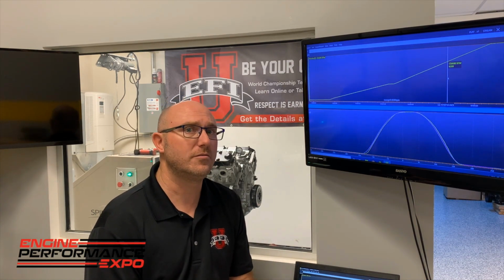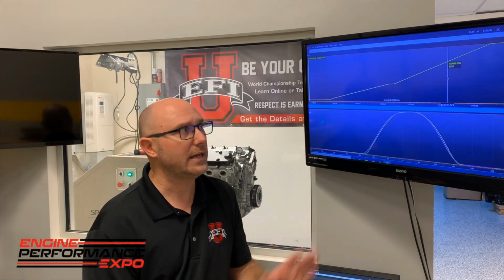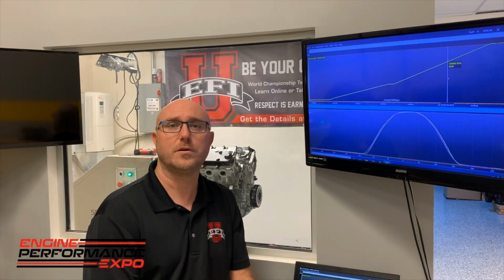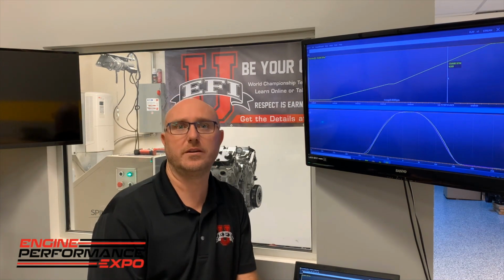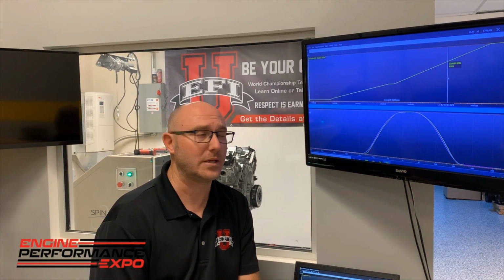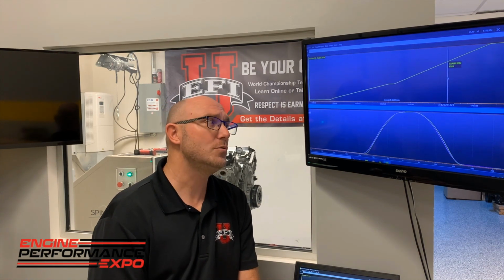Other times what we're looking for is to know what the limit speed of the engine actually is, where we say, okay, I can turn this engine all the way to 9,000 RPM and it's stable, but by the time I get to 9,200 RPM, it's not stable anymore. So people always ask me, well, how do I know what the rev limit of my engine is? There's a lot of factors that determine that, but certainly one of them would be when your valve train goes out of control, it's probably time to stop revving the engine up because you absolutely won't have parts that last very long that way. And you typically also cannot make very much power that way.